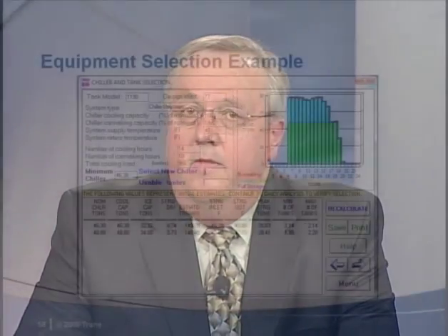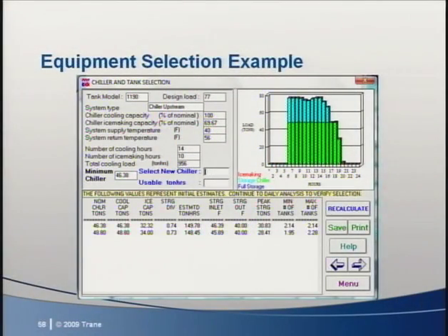Can you show us this in the Ice Pick program? Sure. First, let's look at what happens if we input an actual chiller selection. Then we'll follow that up with increasing the chiller to the next cataloged size. The closest chiller to the minimum capacity required is a nominal 52-ton machine. The chiller catalog reveals that it provides 48 tons at 95-degree ambient during the day and generates about 34 tons of ice each hour at night in 80-degree ambient temperatures. Let's input that data into the Select New Chiller box within the program and see what happens.